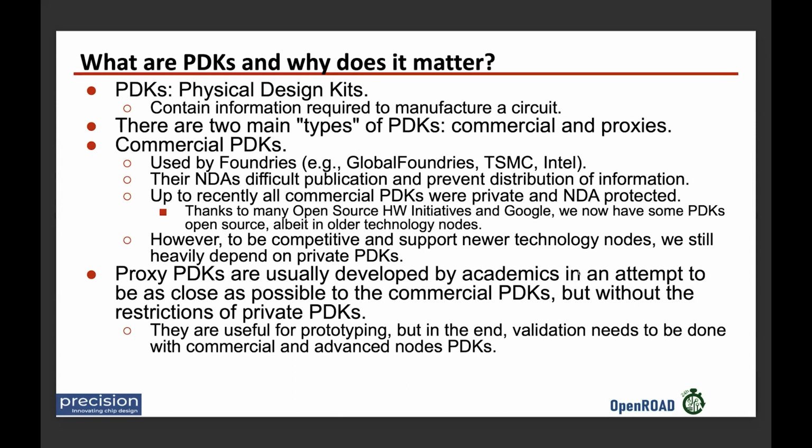Up to recently, all the commercial PDKs were private and NDA protected. But thanks to many open source hardware initiatives and Google, we now have some PDKs that are open source, albeit in certain older technology nodes like 180, 130, and 90 nanometers. However, in order for our EDA to be competitive and support the newer technology nodes, we still heavily depend on private PDKs.